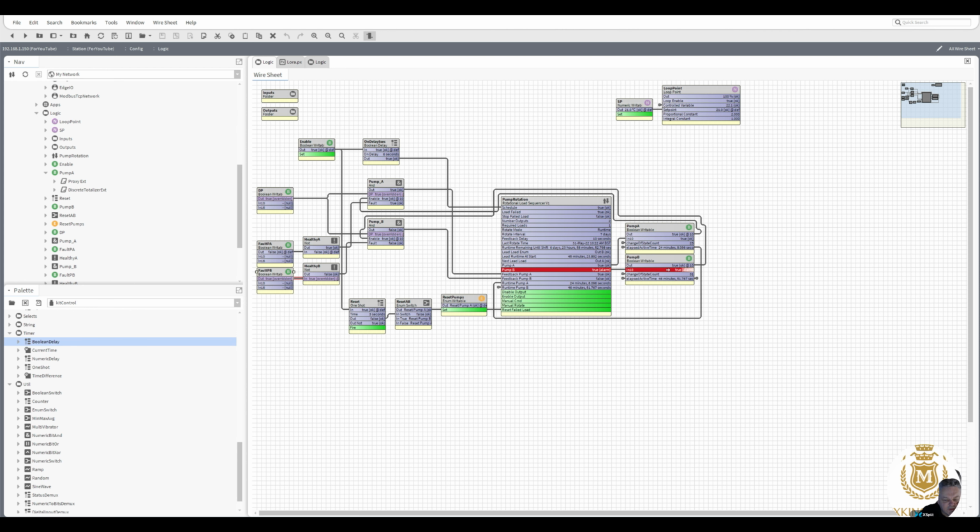This is another thing as well, we don't want to be sending a signal out. If it's in fault, we want that to be false. So we would tie that signal up to an AND gate. Because if that's going to direct it to an output, we don't want to start that pump. We don't want to still keep the enable. I mean, if it's faulty, it's faulty. We want to turn it off. Let's just do that.